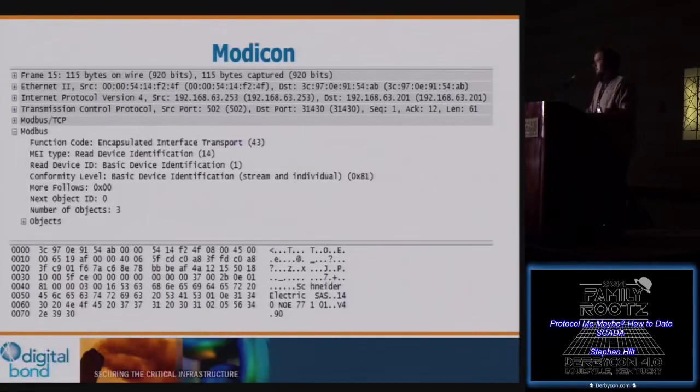Modicons use Modbus. So here's me performing a read identification via function code 43 to a Schneider device. As you can see, there's Schneider Electric SAS 140. It's an NOE card. This is actually one that Digital Bond owns, and we own the Unity Pro software to configure it. So this is packet captures that we did based off our own equipment.